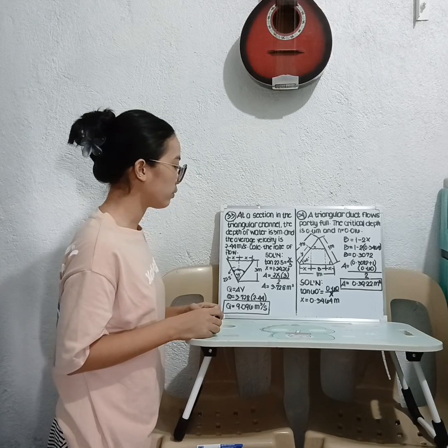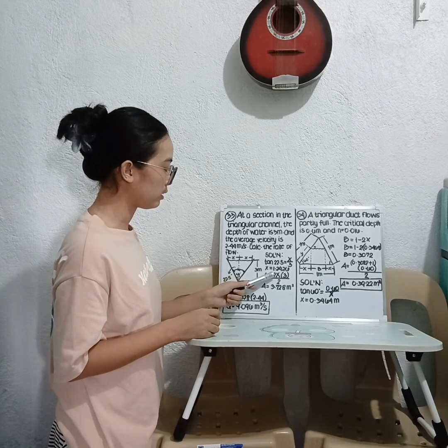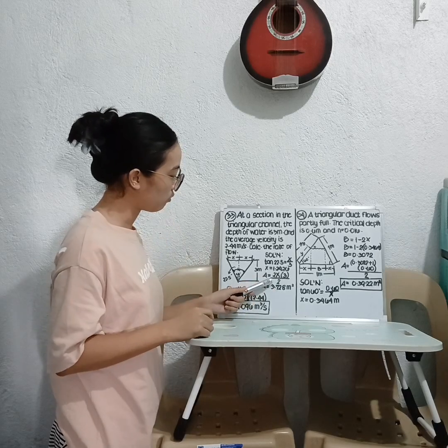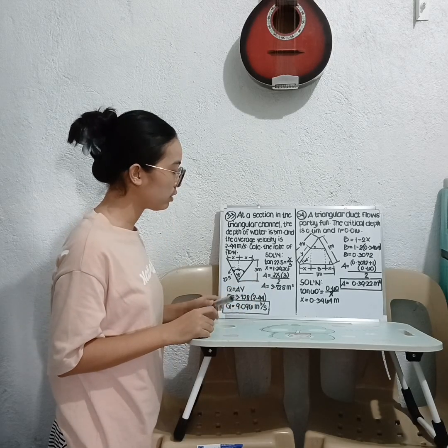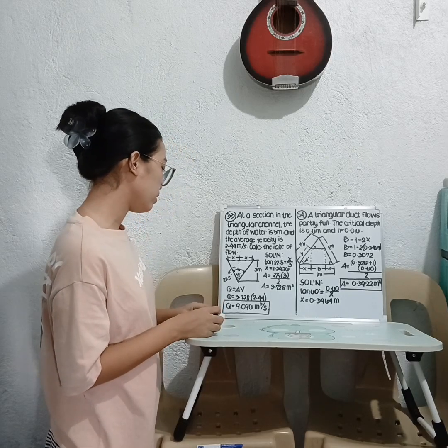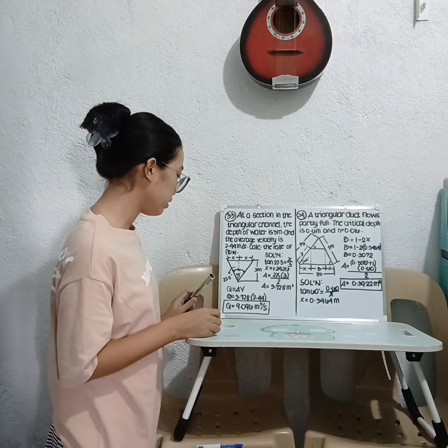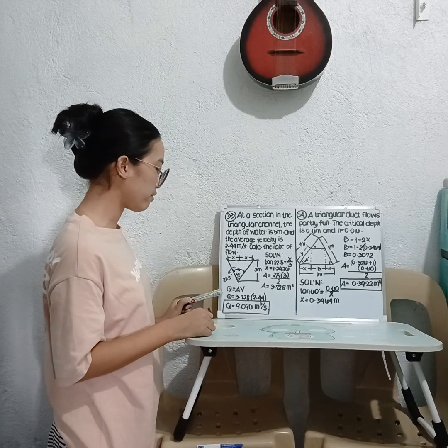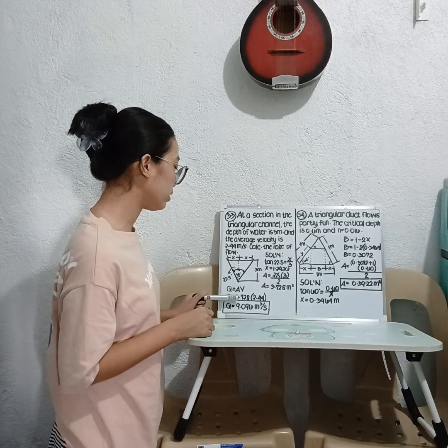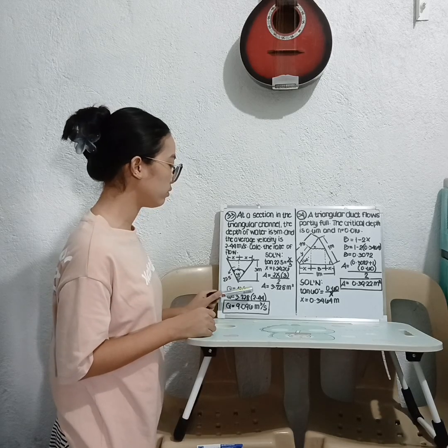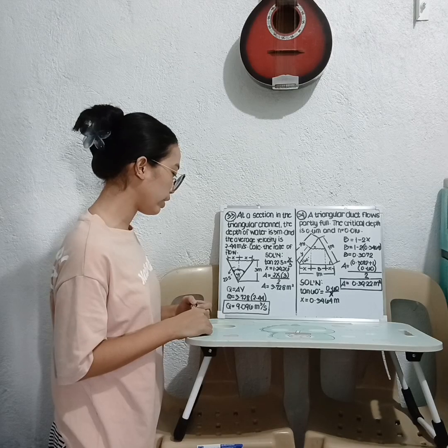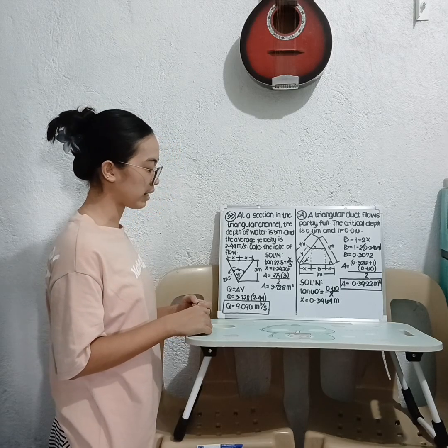Then our area is equal to 2x, substitute the x into the area times 3 over 2. We have area of 3.728 meters squared. Then use the formula of Q is equal to AV. We have Q is equal to area of 3.728 times the velocity of 2.44. We have Q is equal to 9.096 meter cube per second.